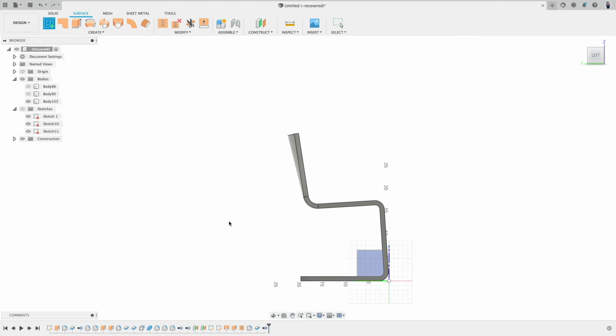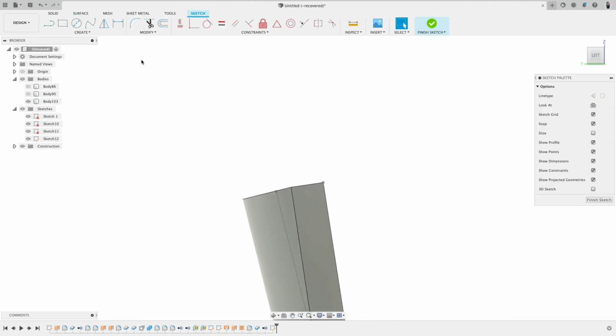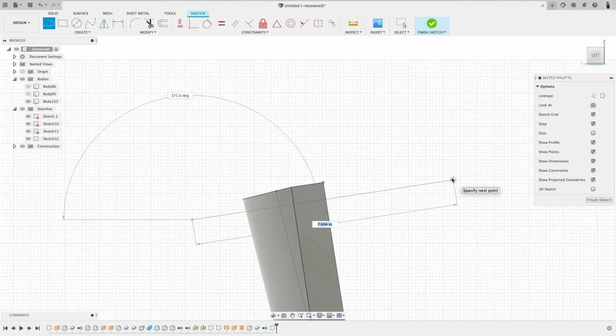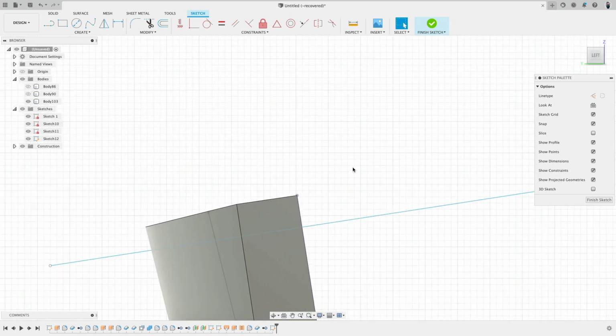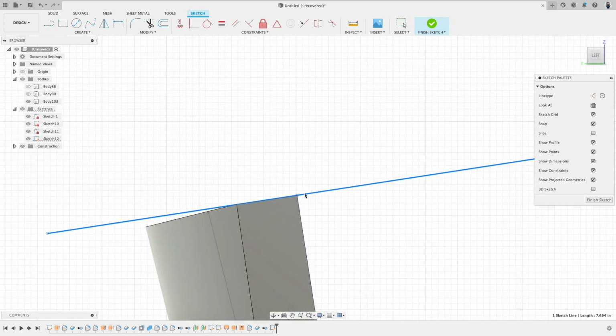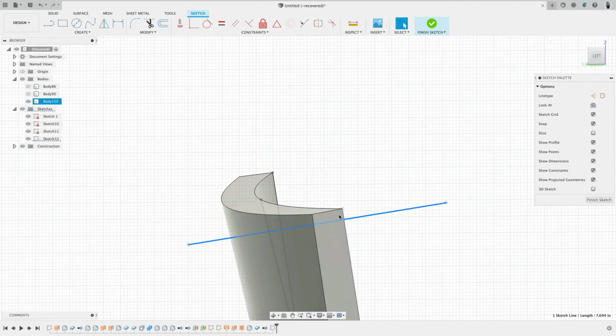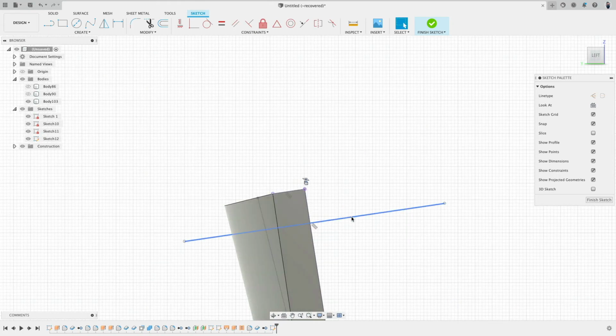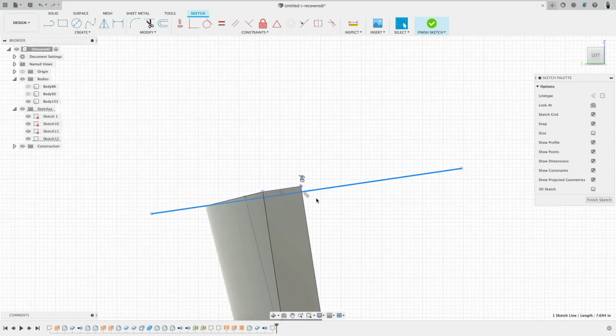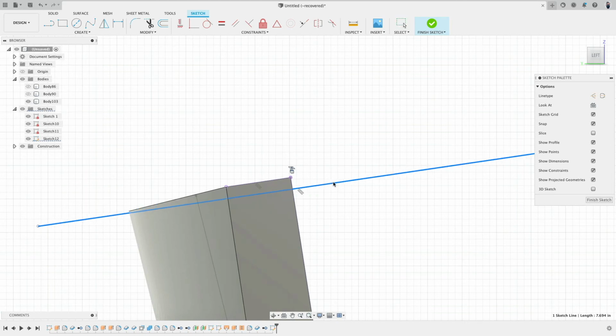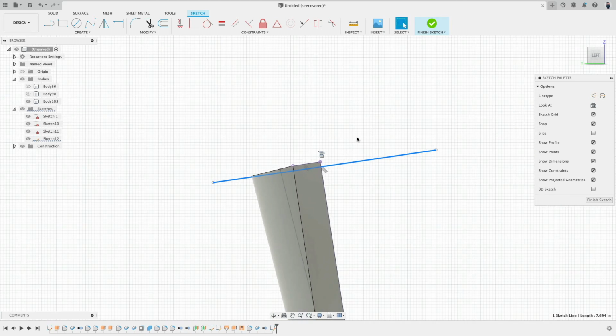At this point, I will create myself a new sketch. There we are. Then I will draw a line like this. I would like to maybe make this really perpendicular to this thing. So I could go project and project this line in. And then these two lines I make parallel. Press escape, and then I can move this one up right to maybe like there. You see, then there it starts